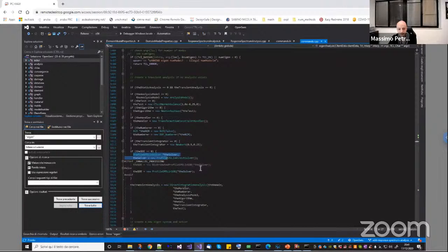The problem is that if you want to do the eigenvalue analysis when your model is not completely linear because it is undergoing a nonlinear stage, probably your system matrix will not be SPD, which is symmetric and positive definite. So that's why typically you can trust the default values, but sometimes they may not work.